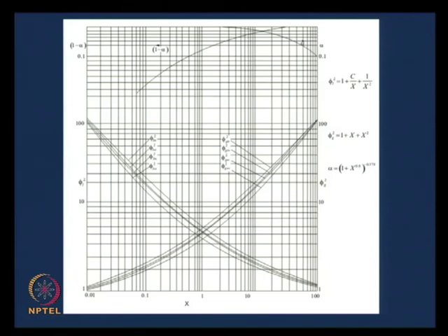When we have some amount of acceleration pressure drop, under that circumstance also it can be used, but remember one thing: the more important the other components of pressure drop become, the less important the frictional component of the pressure drop becomes, the more inaccurate the correlation becomes, because the basic thing was based on the fact that the 2 phase pressure drop primarily comprised of the frictional gradient. So, the moment that is violated, the resulting error becomes more.